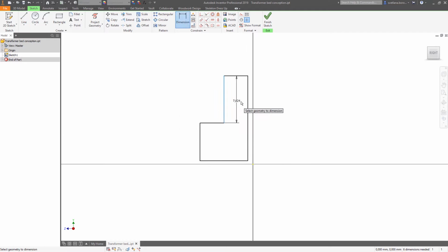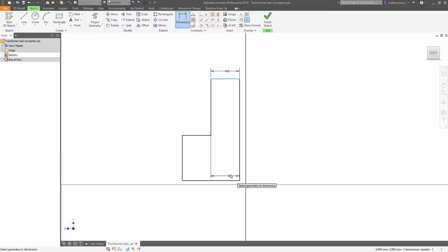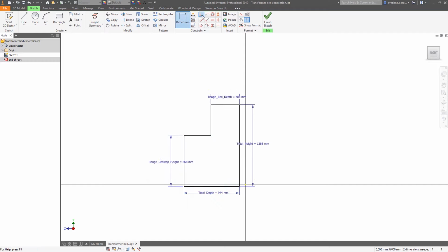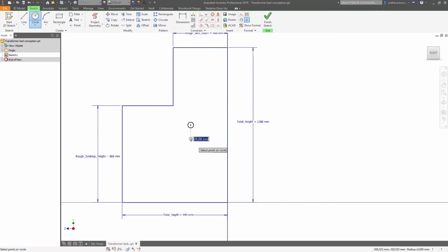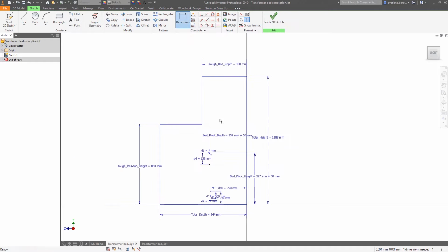This will be a main body, defining a set of parameters which will help you to control the size of each of the items. So we can define the depth, height, etc. When all the parameters have been set, we can apply some constraints if needed, and then we will define pivot points for a hardware. It's a bit unusual, but since we are doing custom hardware, that's why we can use those pivot points as references. Now the geometry can be converted into the block.